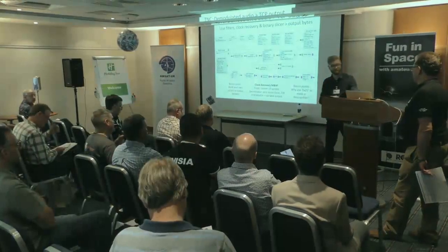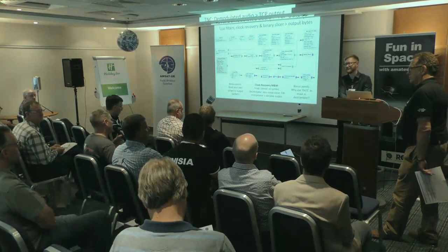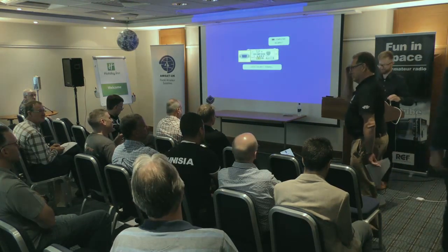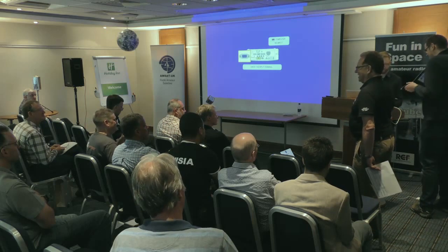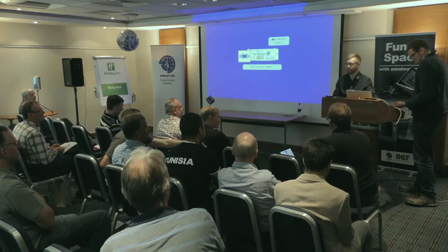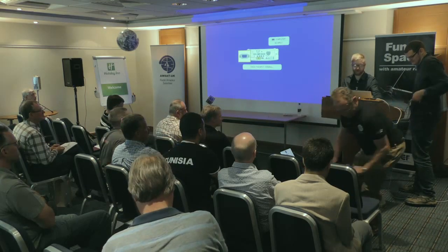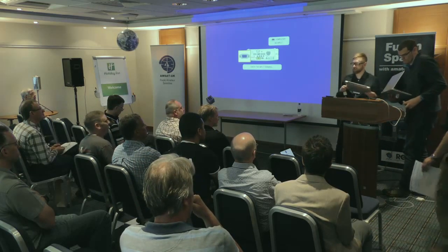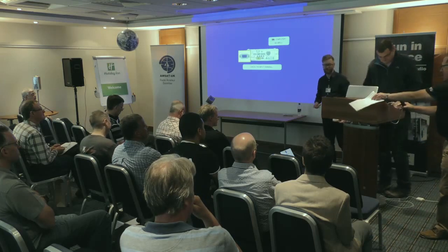May I add one extra bit on that? Sure. Everybody thinks you can reduce it down and keep decimating and keep decimating. If you are going to use any of the GUI sinks that give you a waterfall and all the rest of it, don't go too low, because they can't handle it. Oh, yeah, I've discovered that the hard way. Yeah, I mean, you're probably oversampling by hundreds of times more than you actually need to. If you go down to about 8, that's when it usually starts to fall over.